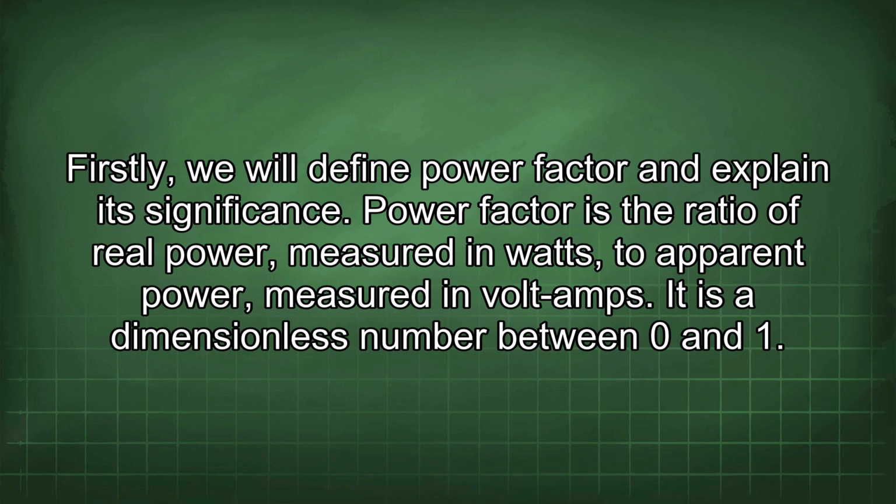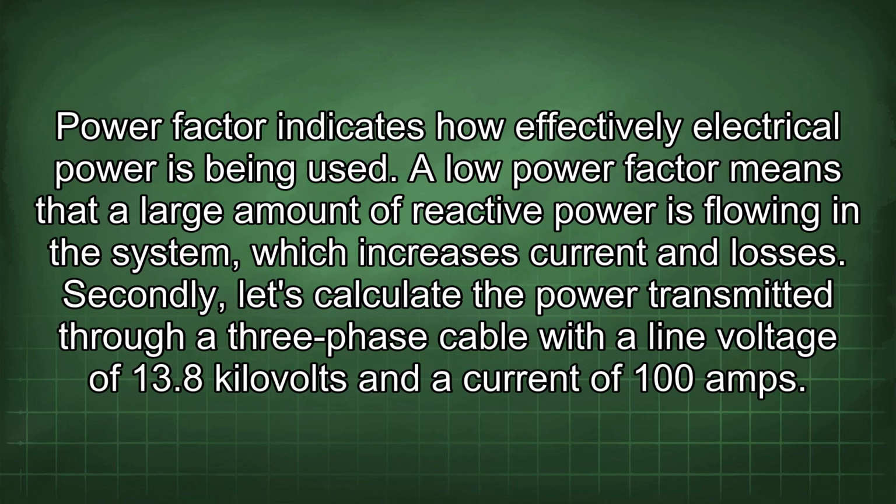Power factor is the ratio of real power, measured in watts, to apparent power, measured in volt amps. It is a dimensionless number between 0 and 1. Power factor indicates how effectively electrical power is being used. A low power factor means that a large amount of reactive power is flowing in the system, which increases current and losses. Secondly, let's calculate the power transmitted through a 3-phase cable with a line voltage of 13.8 kV and a current of 100 amps.